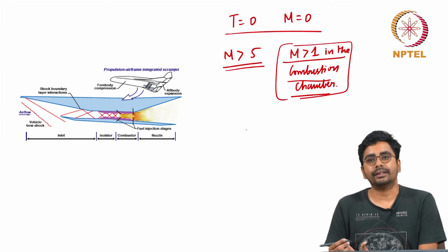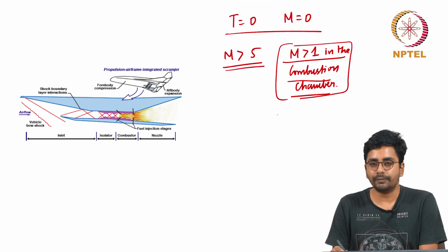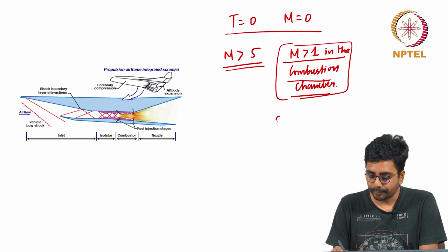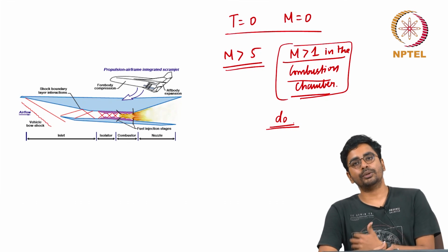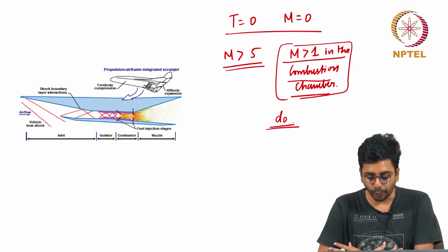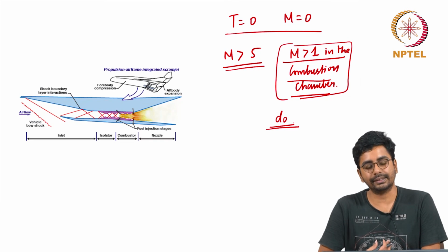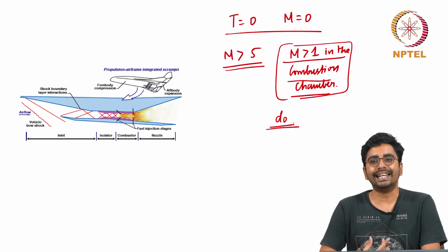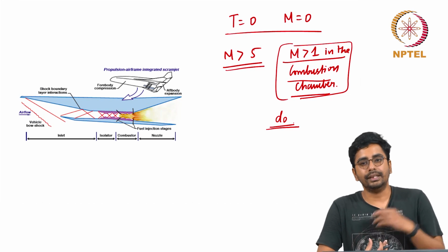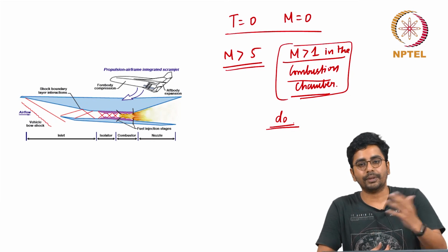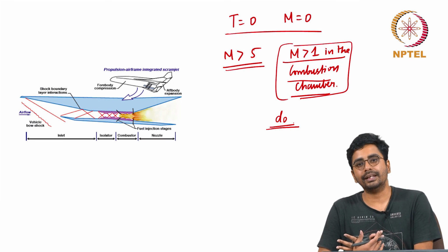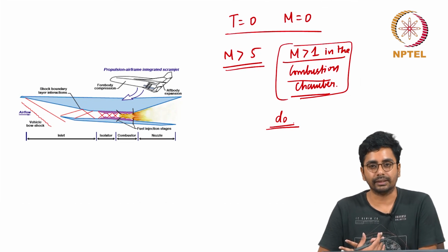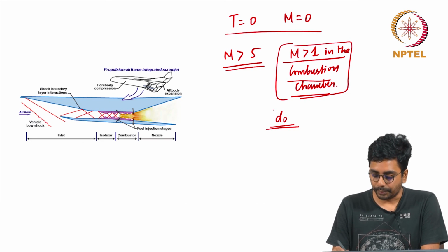In candidate vehicles where liquid fuel is used, again the droplet size controls the heat release. Here the heat release should not be too fast or too slow. The design is in some ways unlike any other propulsion system where the engine is designed separately from the vehicle. A scramjet is a special system where the vehicle design and the engine design must go together. Okay.